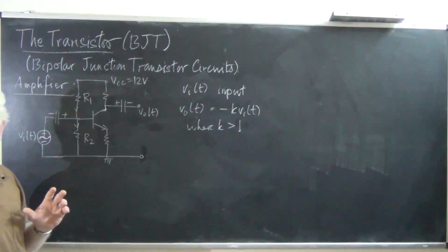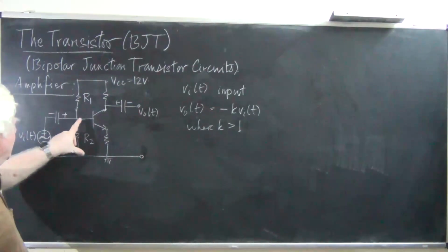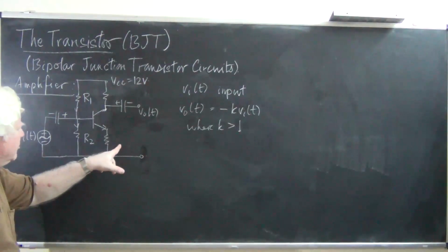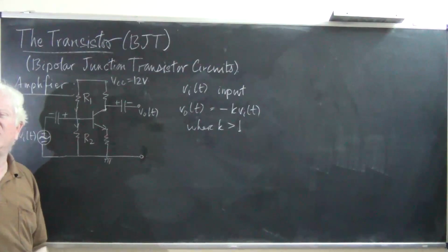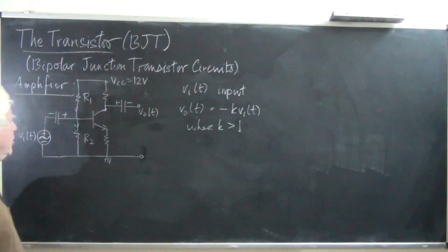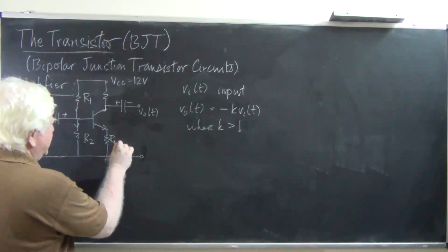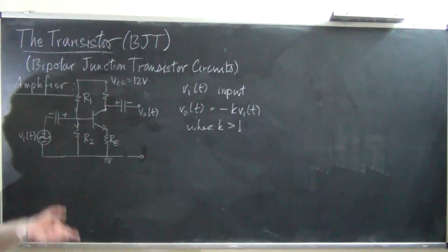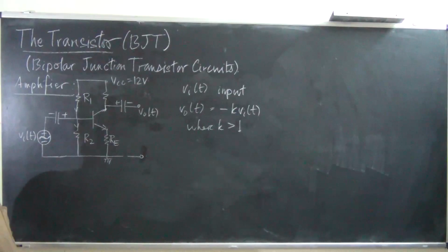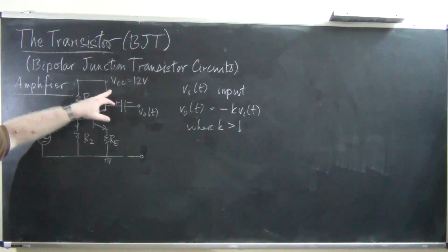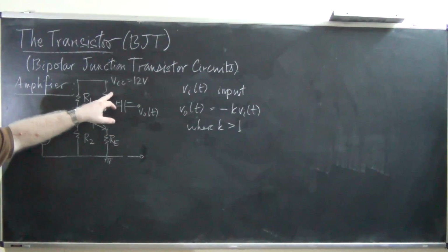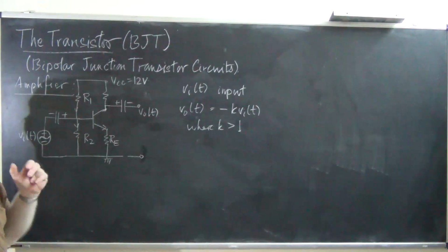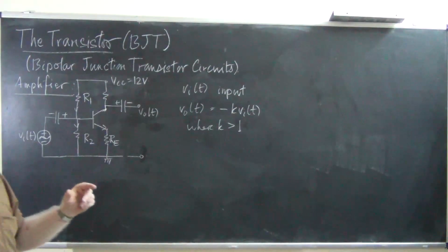The lower part of the voltage is now the base ground voltage, not really the base emitter voltage, because there is also a resistance here whose purpose is a little too complicated to explain. It's called RE, and its purpose is to stabilize the behavior of the transistor under temperature variation. We will not worry about RE right now. The fact, however, is that RE will drop some of the varying collector voltage, which should have actually occurred across the collector resistor, over itself as well, and therefore cause a significant loss of amplification. But there is a workaround for it that we will discuss in the last moments of this presentation.